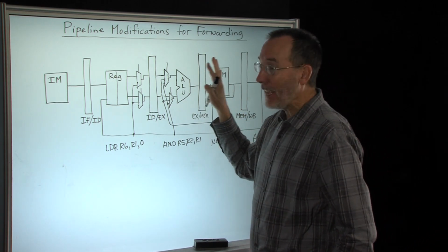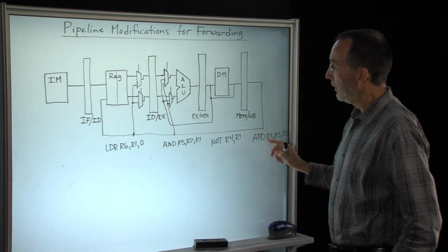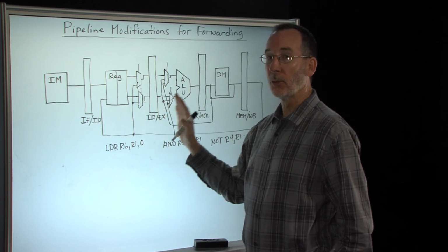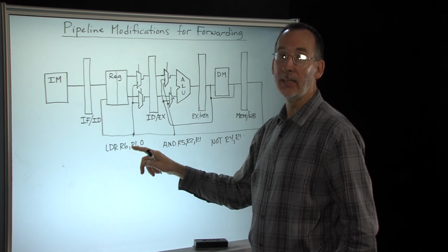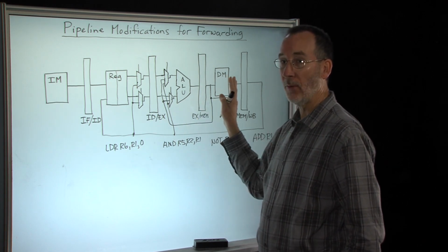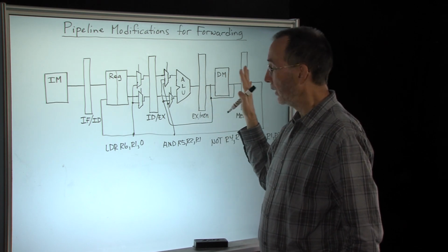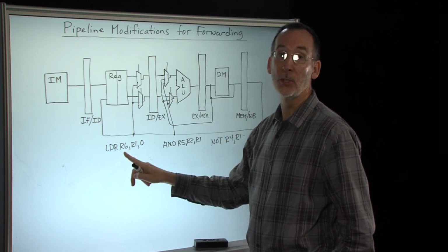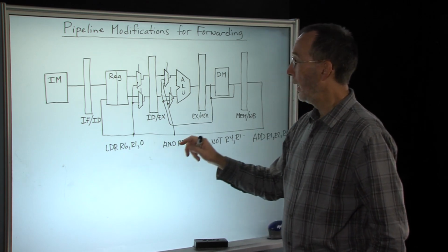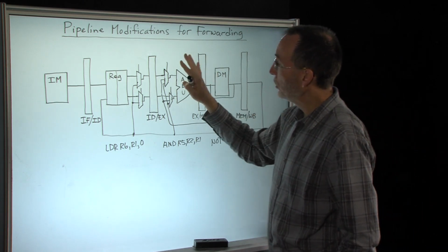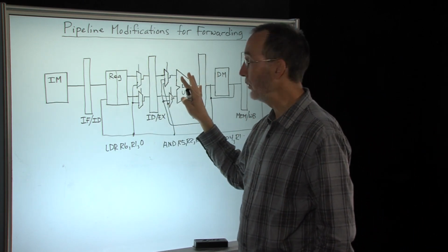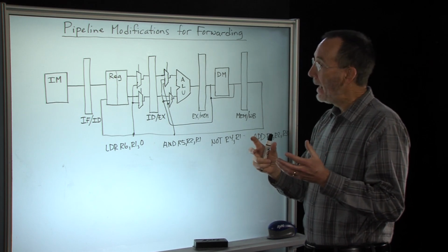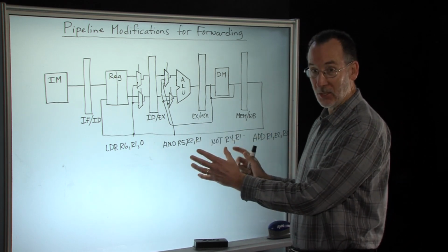Where I have an ALU instruction, such as this add, we need to forward the values back to the other instructions. Now it gets a little trickier when we have LDR instructions that need to be forwarded, and we need additional hardware for that. You can expand this diagram to also handle load and store operations. But you also need to keep in mind all of these control signals. Our control in this pipeline has to be able to detect these dependencies dynamically.